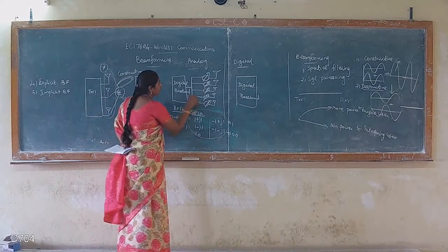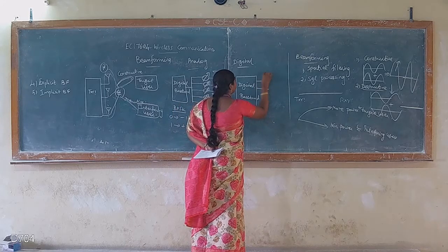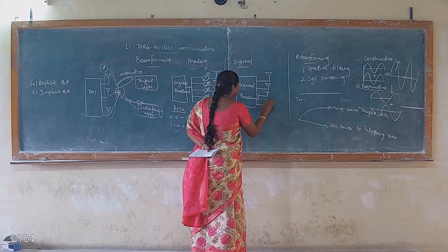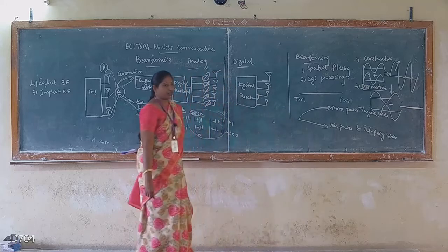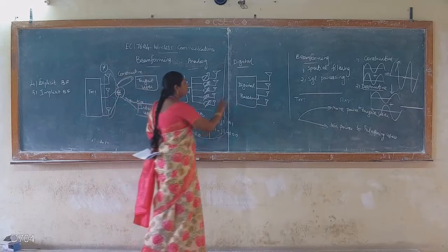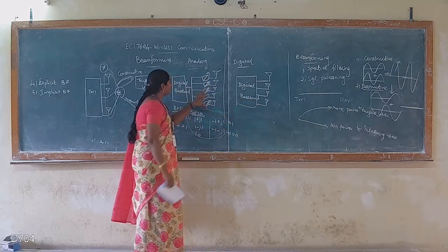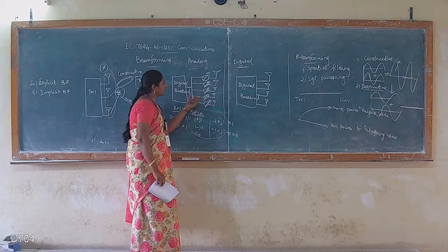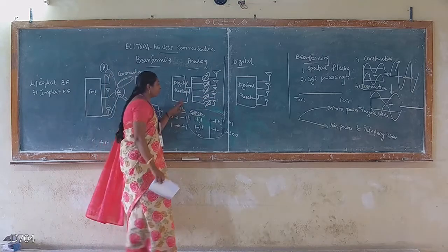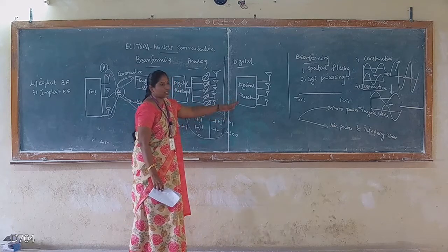But in digital baseband, we transmit different information over the antennas. Here also we use multiple antennas, or an antenna array, and every antenna element transmits different information. That is the basic difference between analog and digital. In digital, all the amplitude and phase variation is done at the digital level; in analog, it is done at the analog level. Another difference is that in analog, all the beamforming operation is done at the RF level, but in digital, it is done in the digital domain.